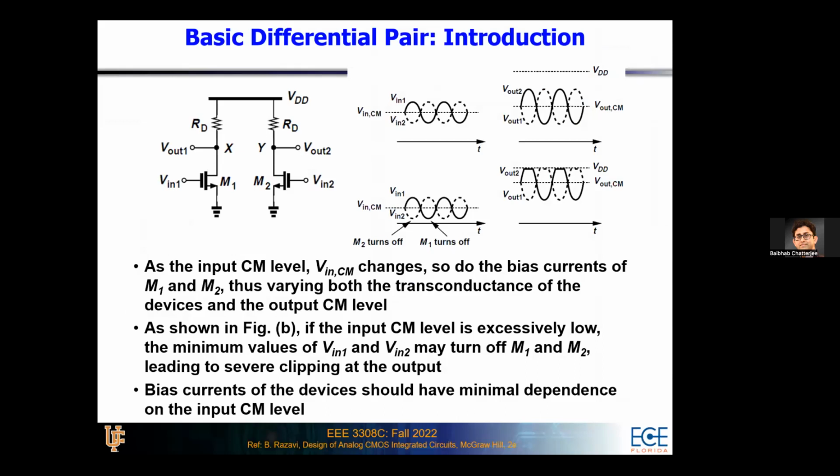Okay, so that's exactly what we are discussing in this slide. As you are taking these outputs, your V1 and V2 may look like this. Your Vout1 and Vout2 will be an amplified version of those two, like in a single-ended fashion. But when you take the difference of those two, that is, you connect your positive terminal of the oscilloscope to Vout1, negative terminal to Vout2, you'll see double the swing of the individual Vout1 and Vout2.